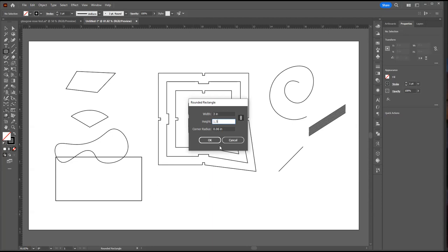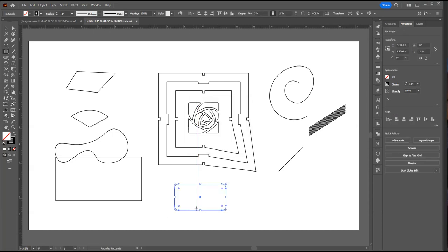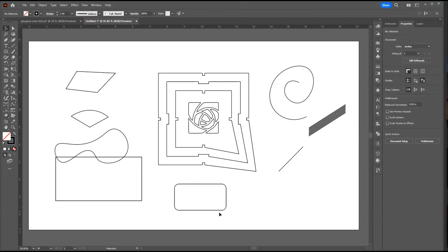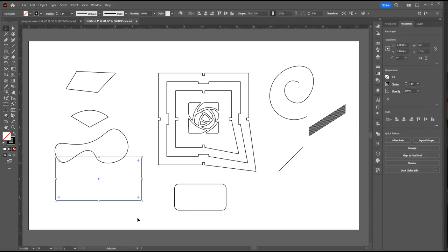Is that right? And this basic is 0.06 inches, which if y'all are using 1/8 wood, you know that that's half of 1/8 inch. So that's 1/16 inch rounding. A lot of people really like the look of 1/4 inch rounding. So we're going to do 0.25 instead, and that's going to make our box. And you can see it's nicely rounded, and you didn't have to mess with that. Messing with it isn't that big a deal, and you can actually get more control if you do.